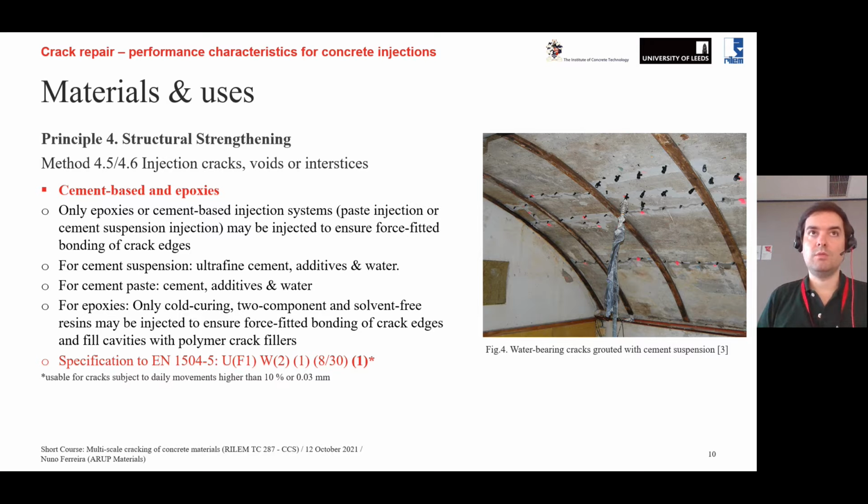So it's quite important to ask the manufacturer for the finest level of the cement, and also to work out the additives and water, because in really high temperature climates, your workability time gets short. For cement paste, this is more to inject large crack widths, for example, maybe in some dam projects that are suffering from ASR. This is probably an interesting solution.